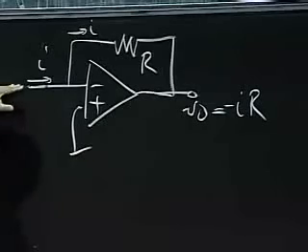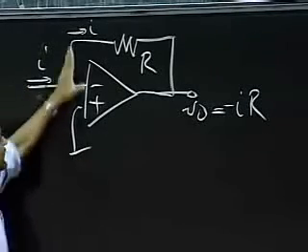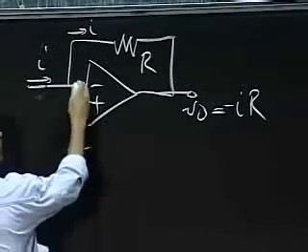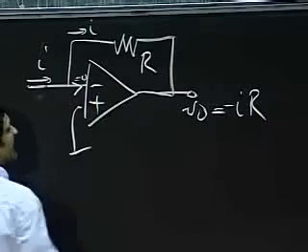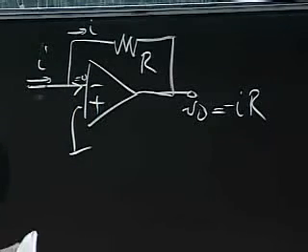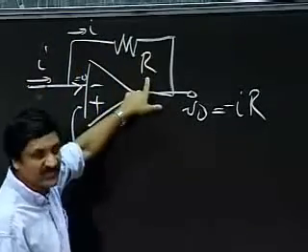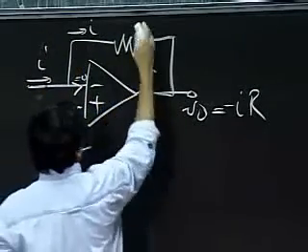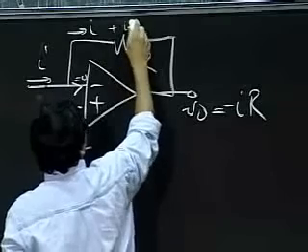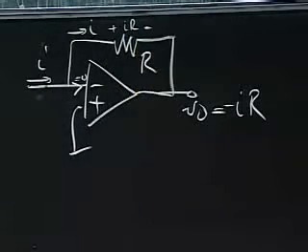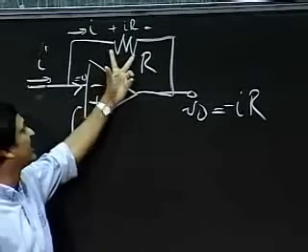Remember, what comes in here must get reflected up because the current going in here is 0. So all the I must come out here. So that I must pump through this resistor. So the drop across this resistor is IR. That's the voltage drop across that resistor.